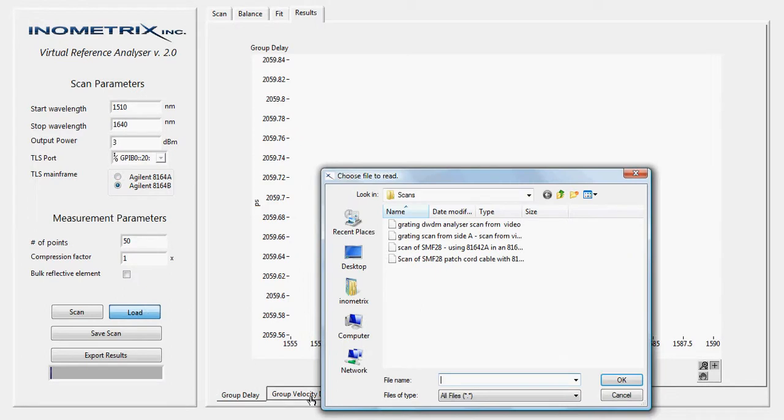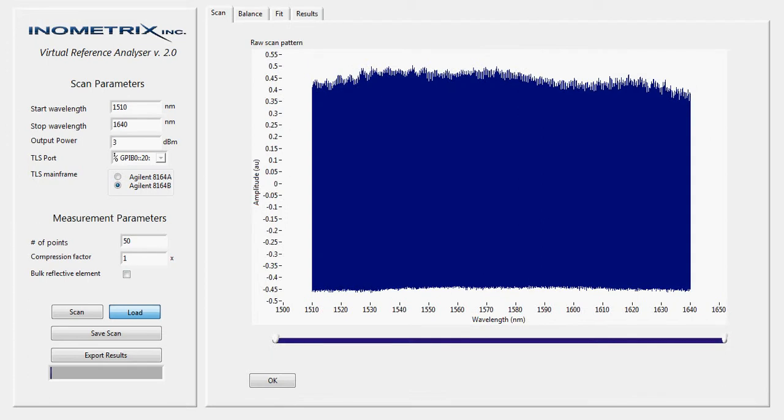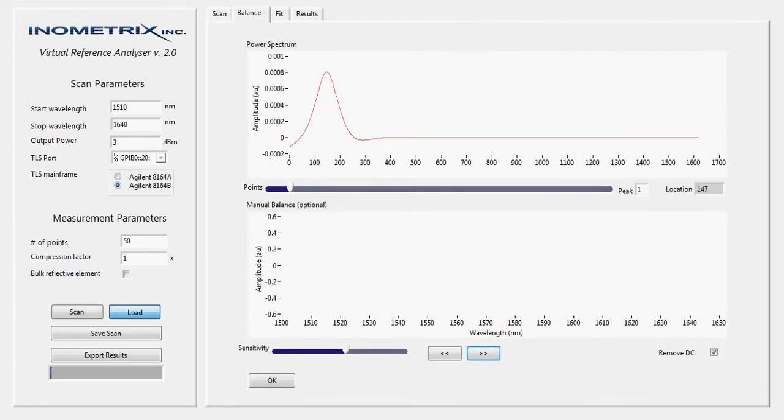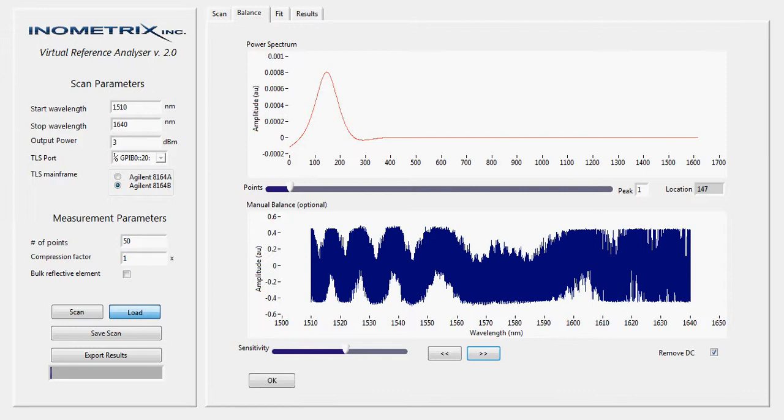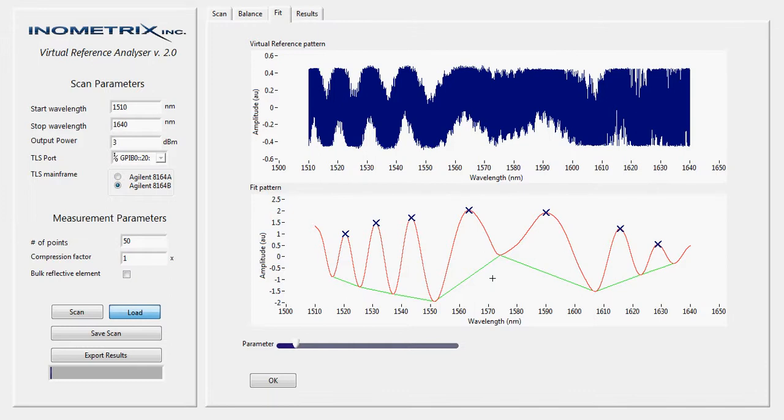So let's run it again. Let's grab the scan, and this time we're going to choose a different fitting here. So let's try and perhaps increase the fit a little bit. Let's go to 24. See, we don't want to go too far. We don't want to fit too much, otherwise we're going to have more than one peak in the center. But we don't want to go too low because that reduces the peak locating accuracy. So we're going to press OK.